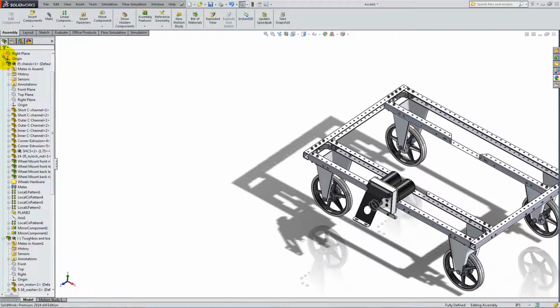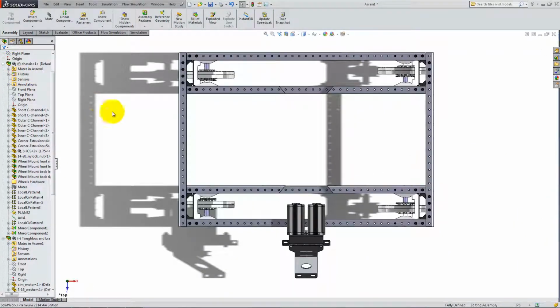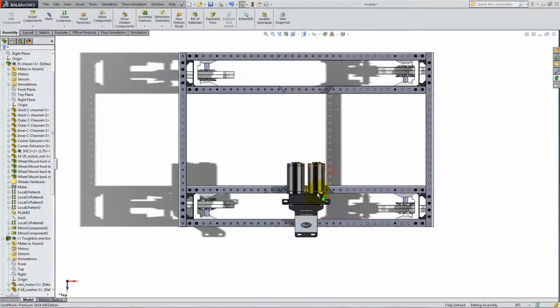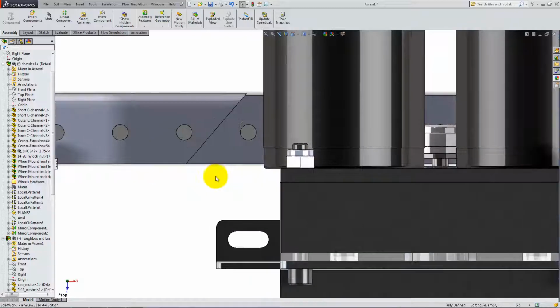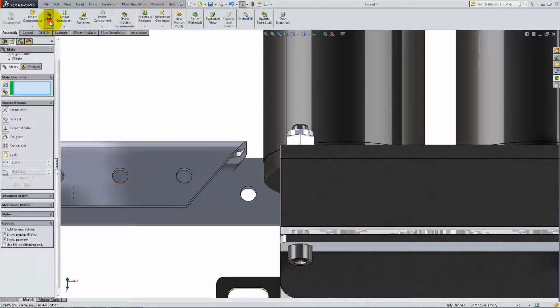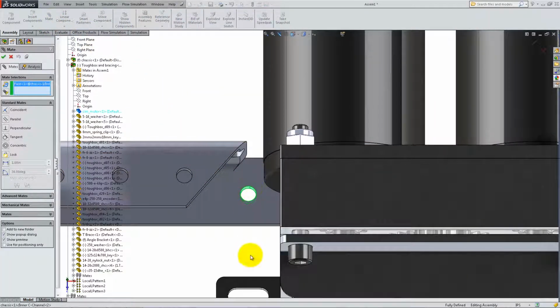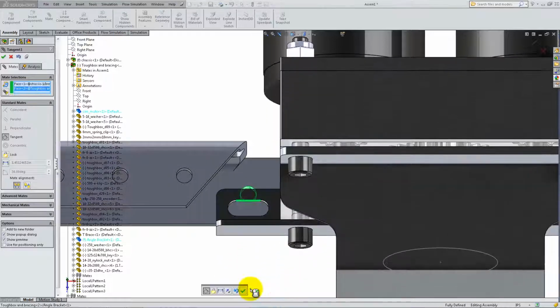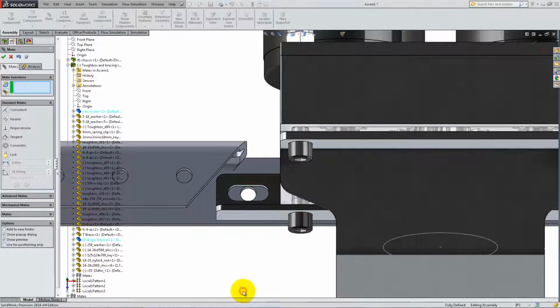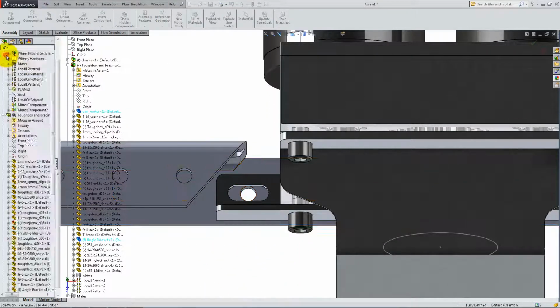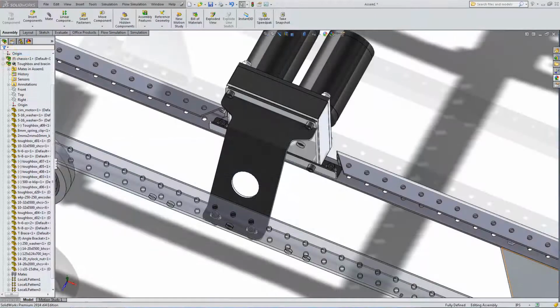Next, go to Top View, zoom in on the end of the angle bracket, and press the up arrow once in order to view the inner surface of the slot. Add a tangent made between the hole in the inner C-frame and the flat part of the slot. Add 2 bolts and nuts between the angle bracket and the inner C-frame, and 2 more between the T-brace and the outer C-frame as shown.